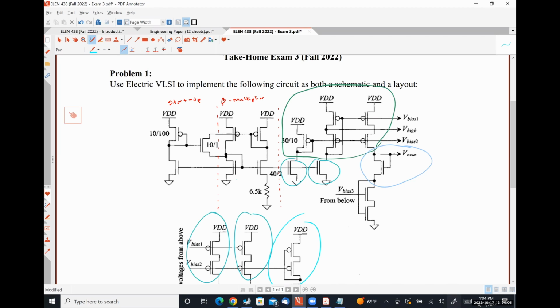We'd get better performance assuming that we have this 2-to-1 ratio of mobilities or close to 2-to-1 ratio of just replacing all of these guys with 20 by 2s. And we're going to do that once we make sure that's the right thing to do by simply doing 2 10 by 2s in parallel with each other so that we can get nice even lines for everything.